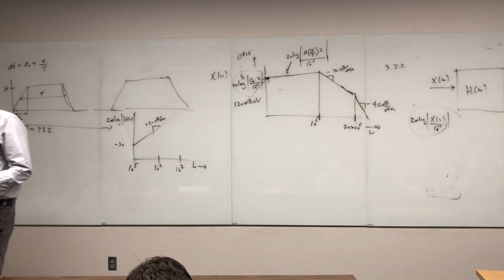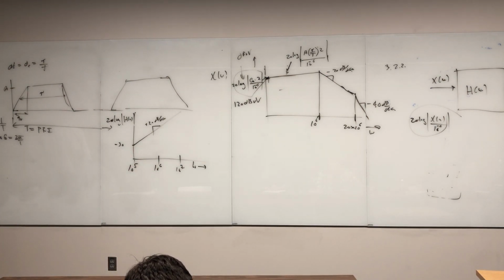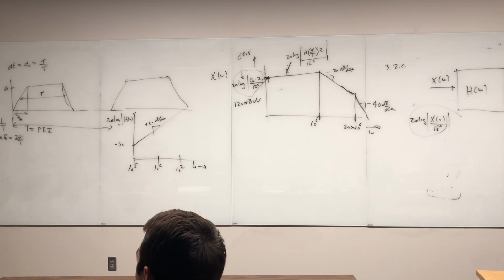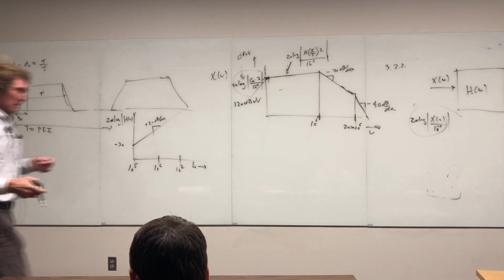You'll see 20 dB per decade, 40 dB, either plus or minus. When you get higher order filters, you'll see 60 dB, 80 dB rate of change. So it's usually 20, 40, 60, 80, stuff like that. That's what you see, either plus or minus.